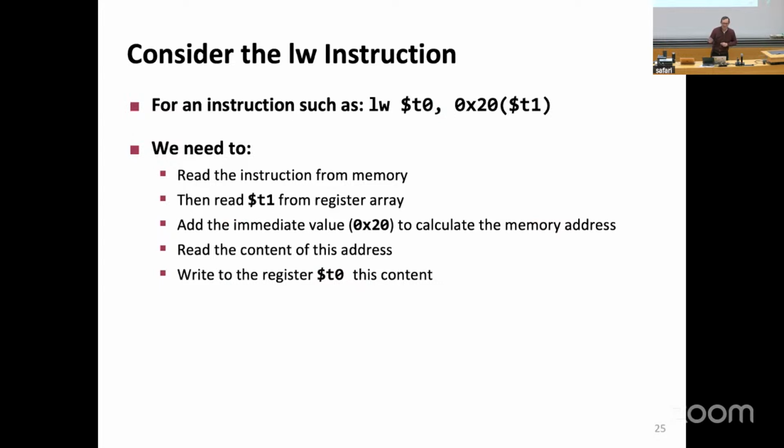In this case, we'll start with a load word instruction, because why not? Last time we started with an add instruction. Why did we start with an add instruction? Why not? Basically, there's no real reason to pick one instruction over the other, because in the end, you're designing a data path for all instructions. And if you're going to execute all instructions, you might as well start with some random instruction also, right? And it's also good to think about, okay, maybe you start with common case instructions, right? Maybe why not is not the best answer. A qualified answer is, which instruction is going to be the most important one for me? Loads, adds, those are pretty common instructions. So you can start with those without any, let's say, downsides.